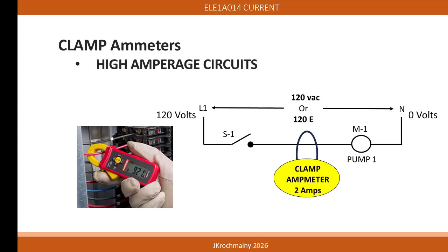On high amperage circuits, such as those involving electrical motors, clamp-on ammeters are used for this measurement. Using these instruments does not expose live electrical conductors to personnel. When amperage flows in the circuit, these meters sample the flux line energy that surrounds the conductor and then provides the amperage value.